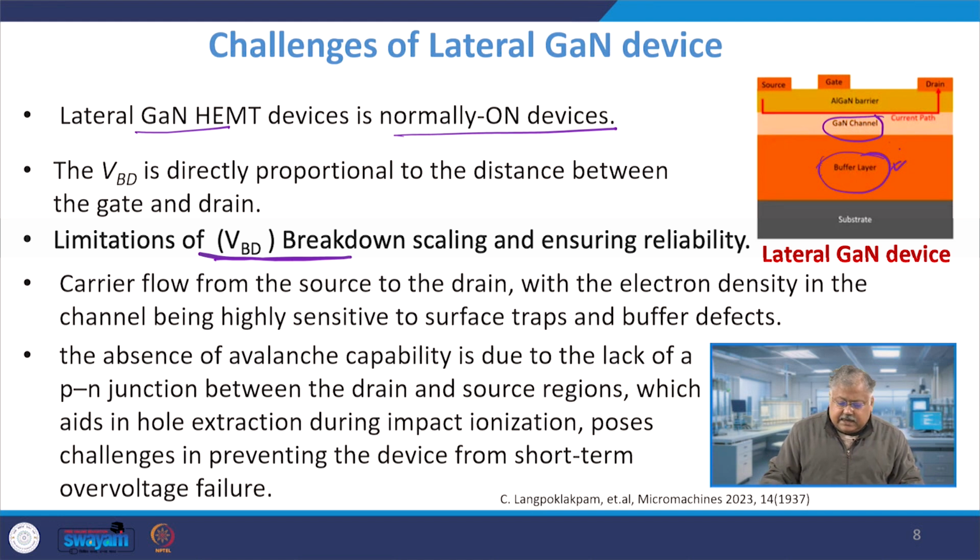Now, since there is no effective p-n junction between the drain and source region, unlike other MOS devices, it's very easy for overvoltage failure. I will tell you what happens.